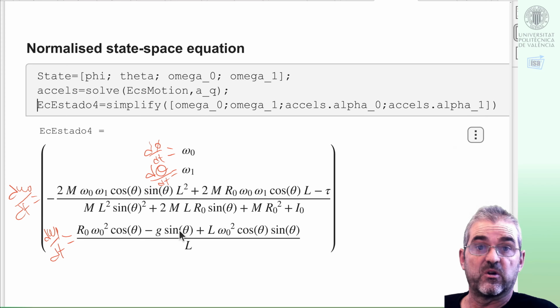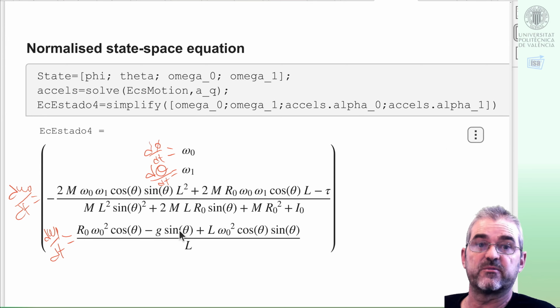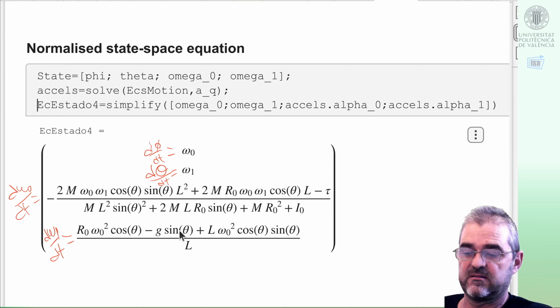So good. The only thing we need is to simulate this with, say, the Runge-Kutta ode45 integrator, but as this is a Symbolic Toolbox object, state equations fourth order, then we need to do a little bit of bookkeeping to transform that to ordinary numerical functions and expressions in order to carry out numerical simulation. So let's do it in a separate Matlab file as follows.